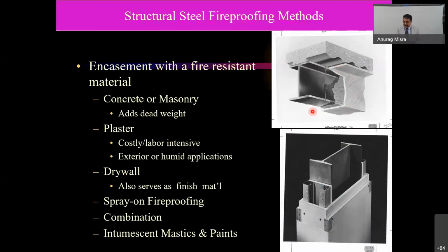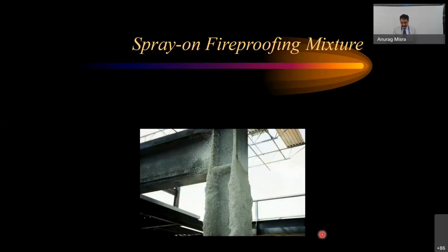Also, this type of cladding is being used for fire resistance. If you are going for such panels, then on the outer side of this, you either put some sacrificial or architectural feature on it, or simply do the painting, or put some aluminum composite if your budget allows. So this is also to deal with fire protection.